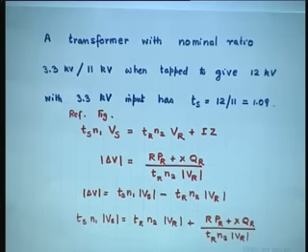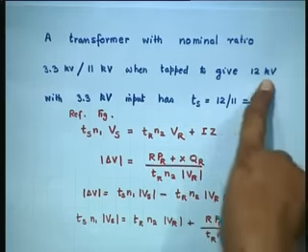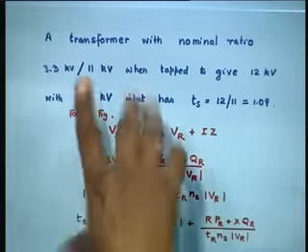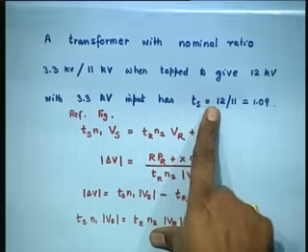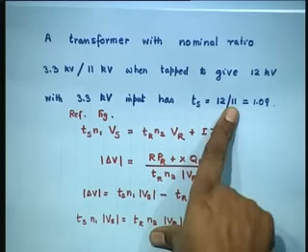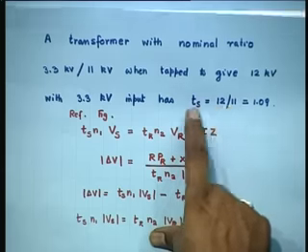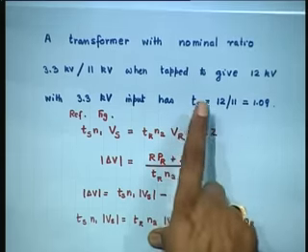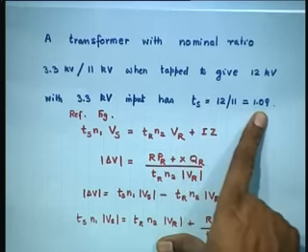So, this much value of Ts is required in case you need 12 kV instead of 11 kV, because 11 kV you will get anyway because of the original turns ratio. But suppose you want higher, as I said, I want 410. So, I can always calculate Ts as 410 upon whatever, 11, 33, 25 kV depending on the value. So, I will get the value of Ts. So, I must adjust my Ts taps to a value of 1.09.